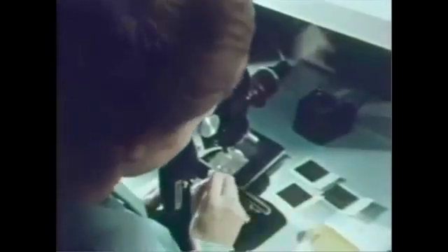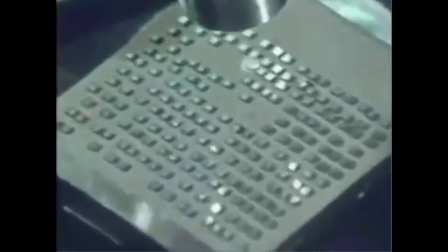We then scribe the wafer using a diamond point in the scribing machine. After separating, cleaning, and drying the integrated circuits, we fish out the ones that are bad. If we have been successful to this point, we have a high yield of good ones.